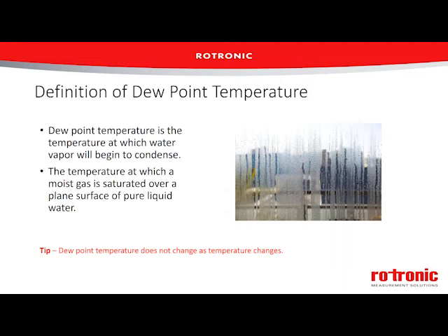Now, even though we are talking about a water content measurement, our units for dew point are in degrees C or degrees Fahrenheit, so it appears as a temperature measurement because we're actually reporting the temperature of the air. Now, one of the things about dew point, though, is while it is a temperature measurement, the value for dew point of a gas is not temperature dependent.